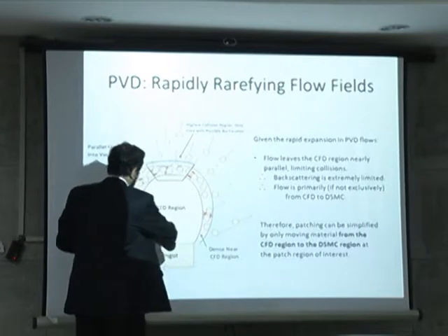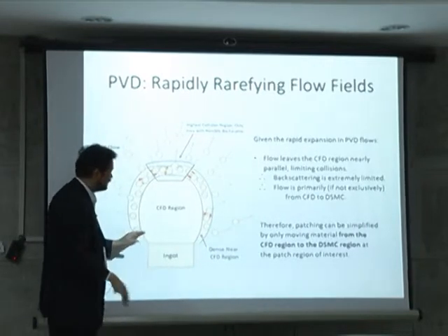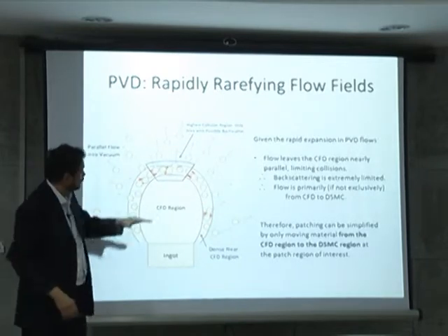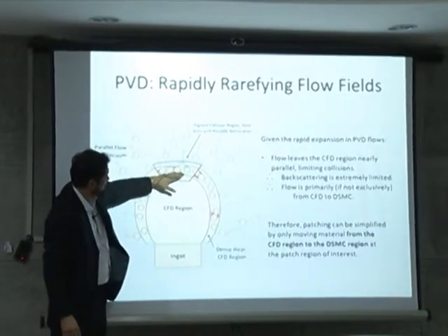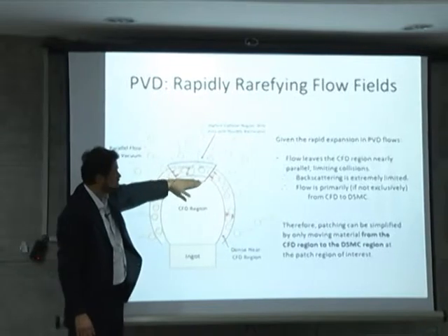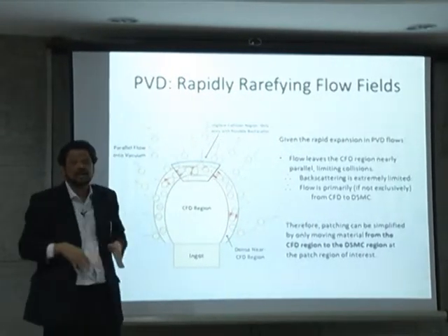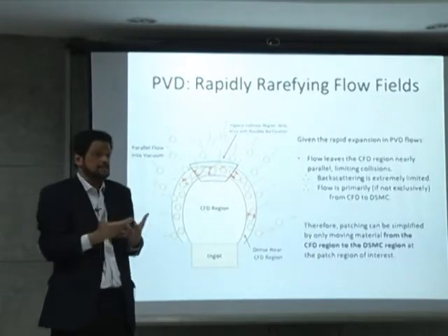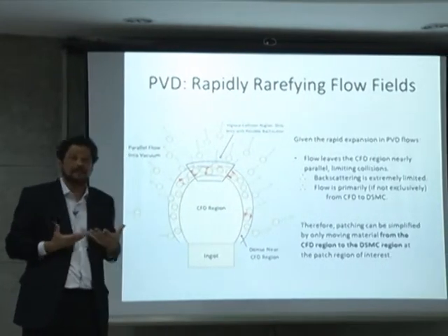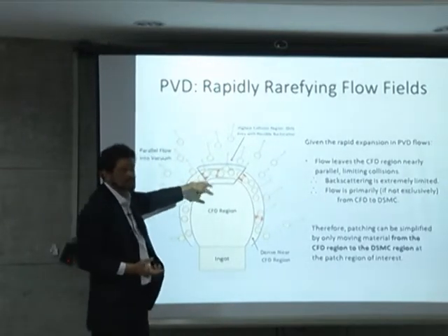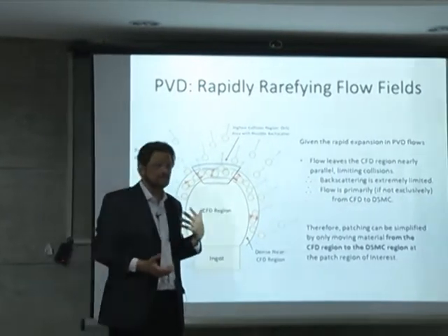Okay. So this is the CFD region, no problem, you can calculate it. This is the DSMC region, you can do it. But what happens at the interface? On one side there is continuum mechanics, on the other side there is not. Where it meets, how do you define that? How do you find out? Because it's not given. You have to mathematically find it. And what kind of boundary condition will you use, that was the biggest headache in the whole thing.